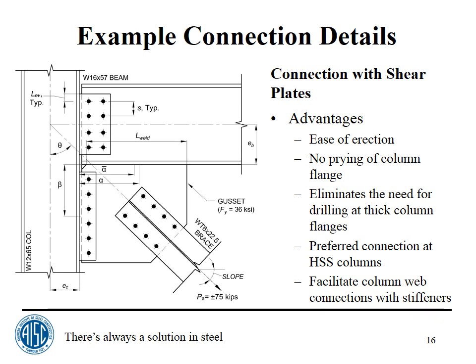We've had erectors tell us that they would give us a deduct of $50 a beam if we could convert a job from double clips to shear plates, to shear tabs. Generally the conventional shear tab. It's just a lot simpler to erect.